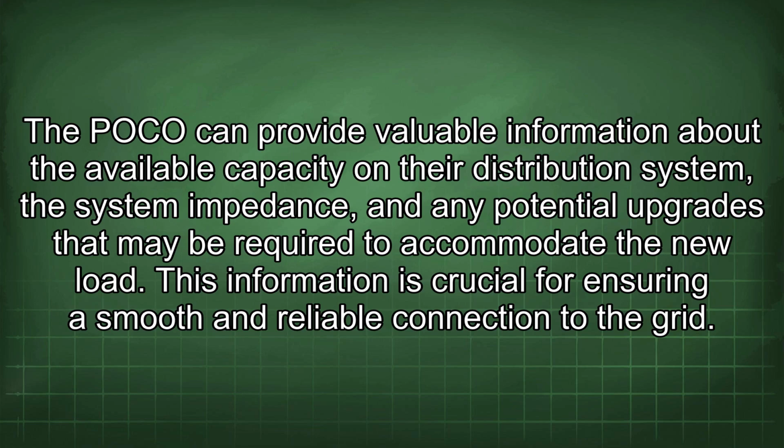The POCO can provide valuable information about the available capacity on their distribution system, the system impedance, and any potential upgrades that may be required to accommodate the new load. This information is crucial for ensuring a smooth and reliable connection to the grid.